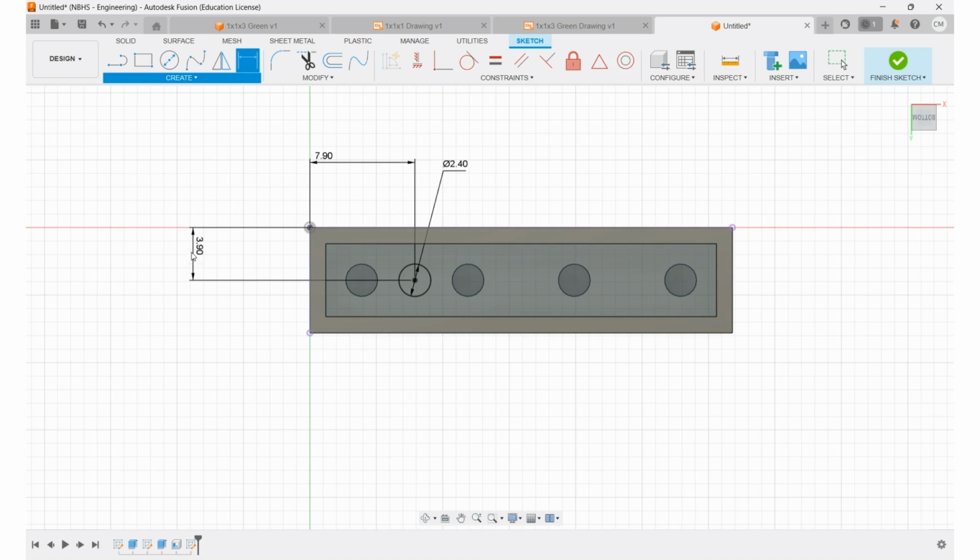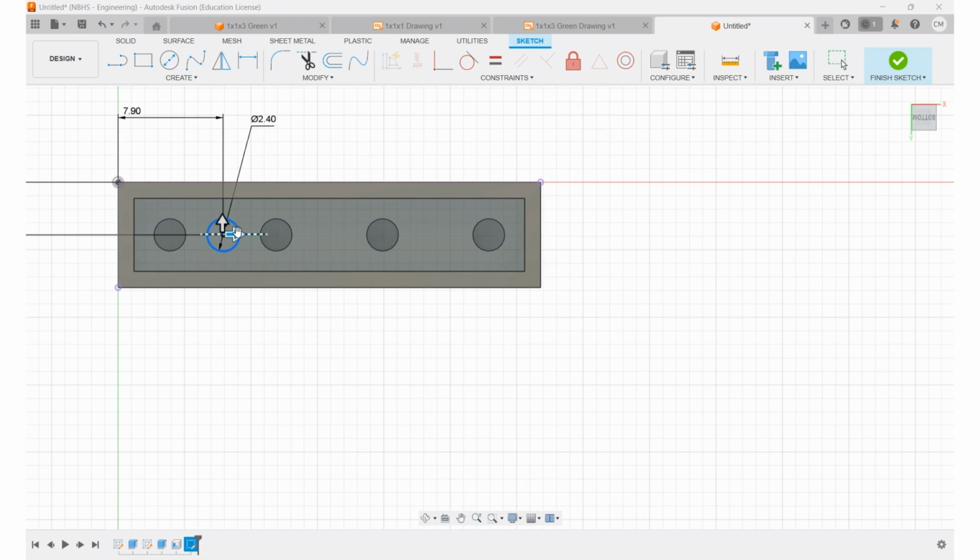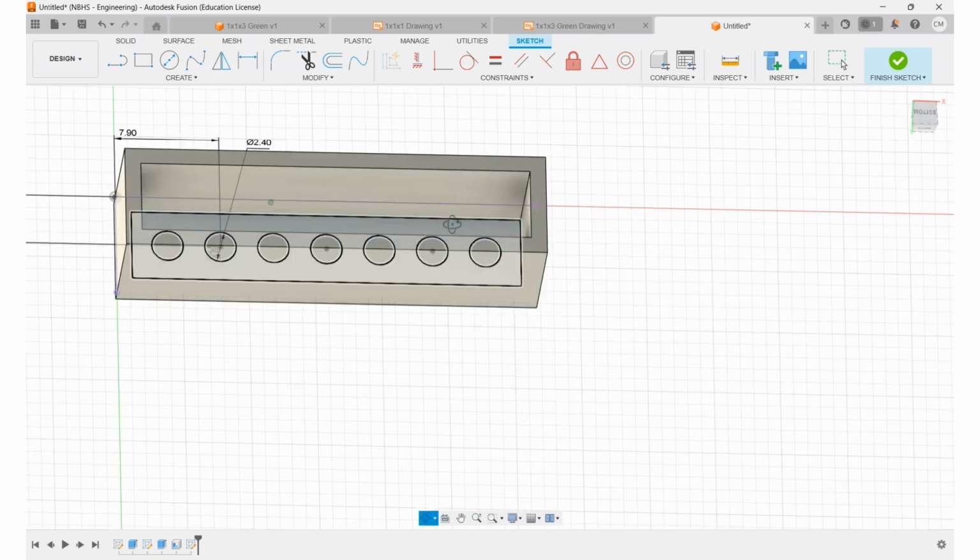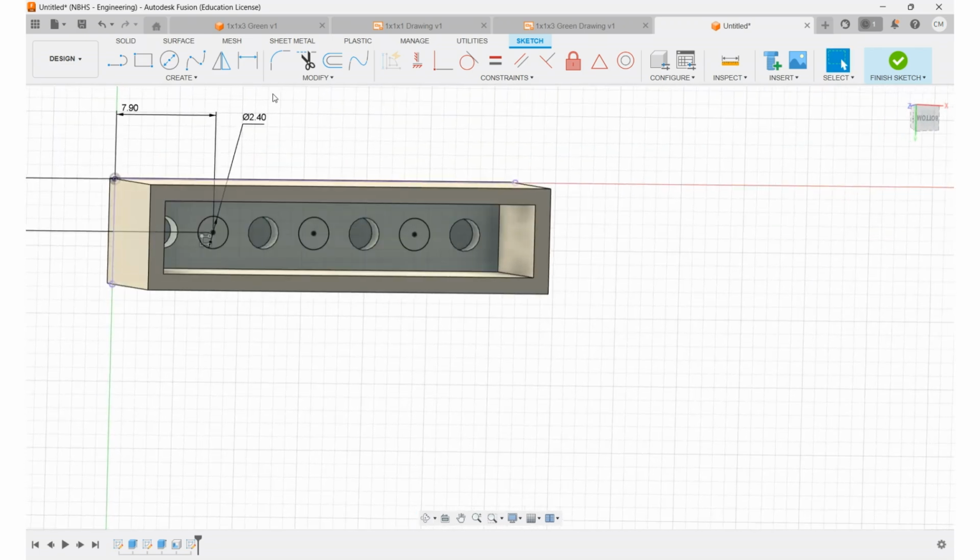I'm going to go ahead and use my pattern tool. I do love my rectangular pattern tool. And I can go ahead and pull this down. By default, Fusion chooses three of any object as the number, which works out perfectly for this one. I'm just going to pull it down a multiple of 8 until I know where it needs to be. That's going to be here. All right, you can see that all of my studs or retention posts are in there dimensioned.